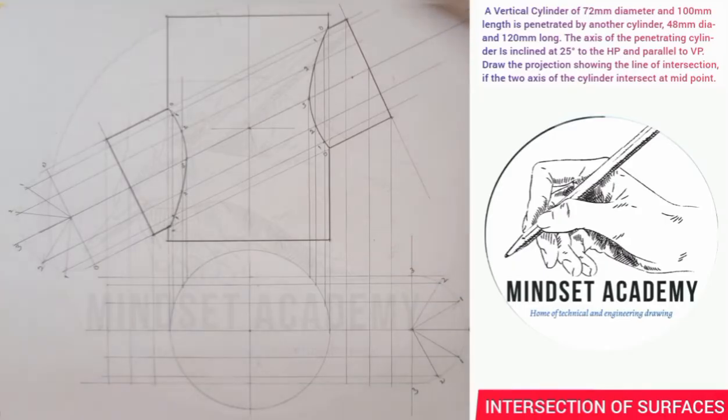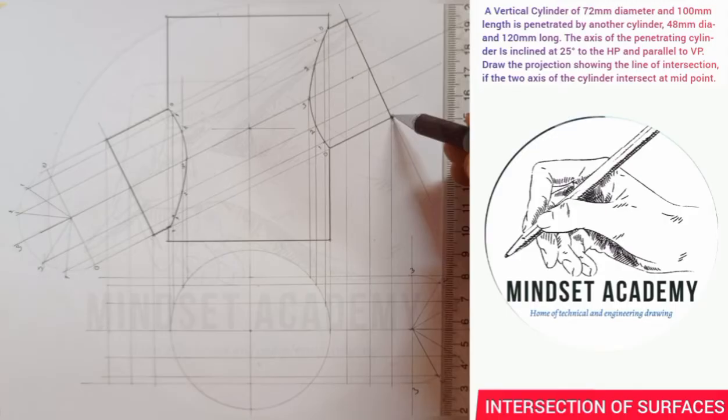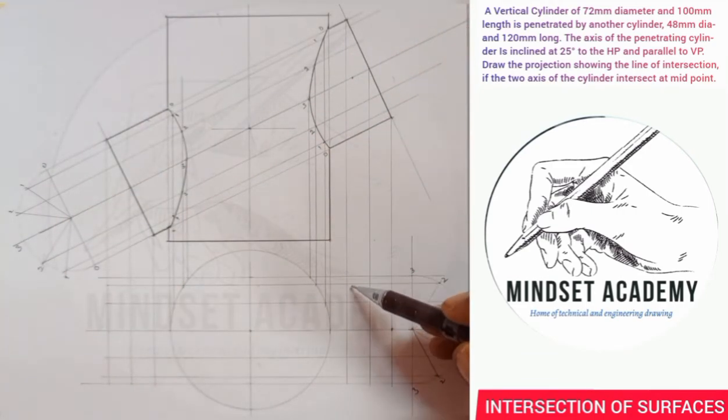So the next thing we'll do is to draw the plan. When you're looking at this from the top, this way, you see an arc being formed here. So what am I going to do? I'll start projecting those points down. Don't forget this is the line of 0. If I project line of 0 down, this is where 0 meets 0. And the other 0 also, bring it down, where 0 meets 0.